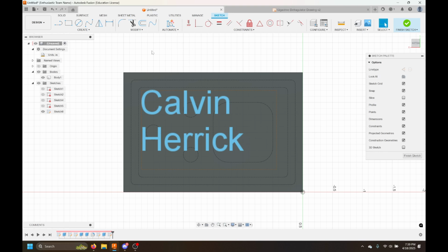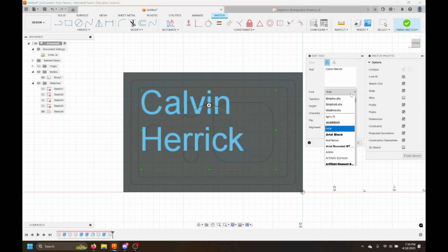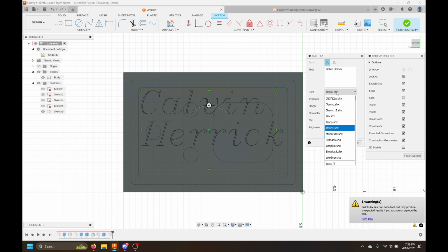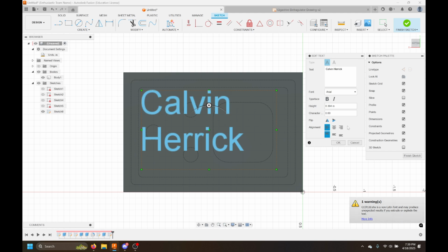Oh, and Andrew, I figured out how to move your engraving bit along a path. It's a font. It's these SHX fonts. Any of these fonts are just lines. Oh my gosh, I will 100% use that for Expo. That's wonderful. Yeah. I did not figure out how to actually put the chamfer bit going along the line. But you can make the lines, that's what's important. If you make it with an end mill in Fusion and put a chamfer bit in your machine, it'll work.